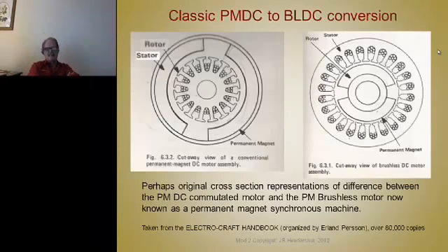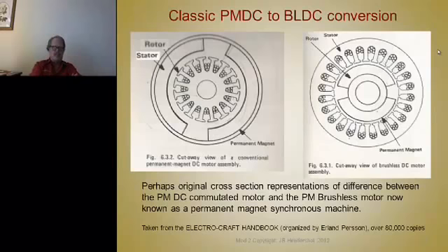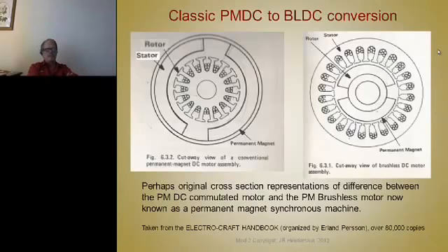In fact, what you concentrated on when you designed these brushless motors in those days was to get a high winding factor, high efficiency, and low losses and good performance, good torque versus amp. You wanted to keep the losses as low as possible, and you didn't really care all that much what the back EMF looked like. It wasn't important.